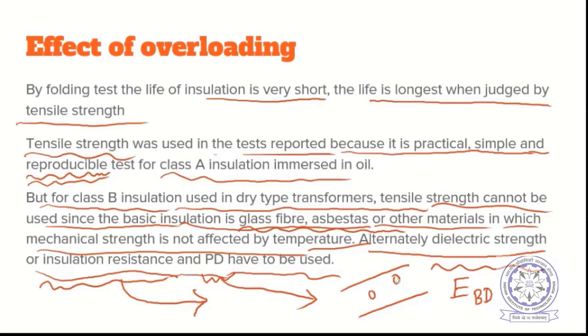These gaps will break down before the solid insulation, because the breakdown strength of air is less than that of solid. So inside the void, these frequent breakdowns will happen.